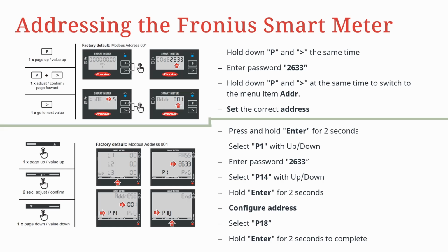So here you have to set the correct address, hold down enter for 2 seconds for confirmation, and after this you select the menu P18, which is for closing the setup menu, and hold down enter for 2 seconds to complete.